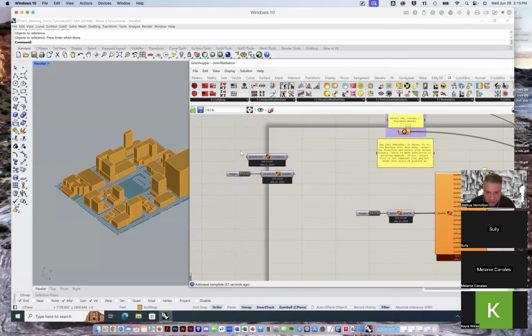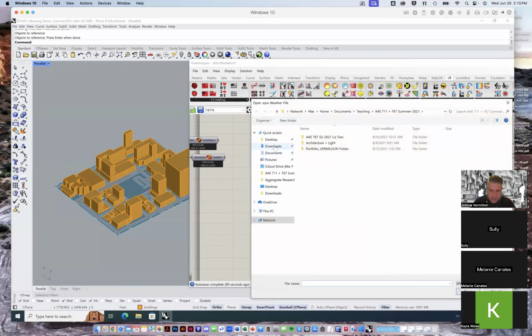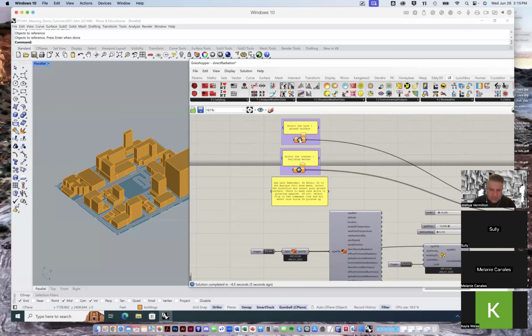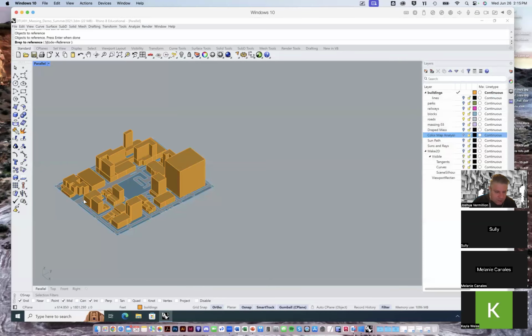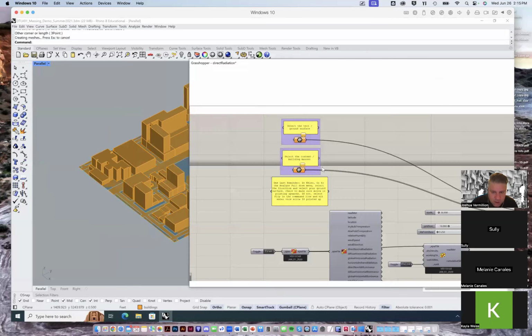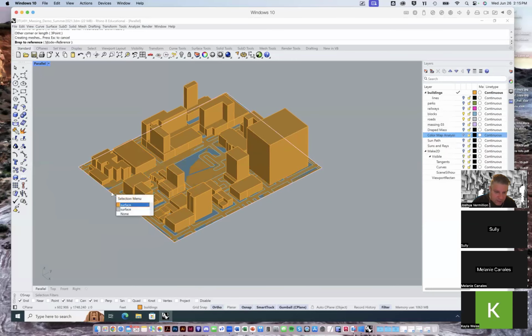We've already downloaded a weather file. So here I'll turn this to true and point it to that weather file again. There we are. Now we can select the test or ground surface. In this case, I'll set one polysurface here. And let's see if I can actually just make one while in this tool. I'll just do that. Yeah, okay, set one. And I'll go ahead and just select it. Surface.